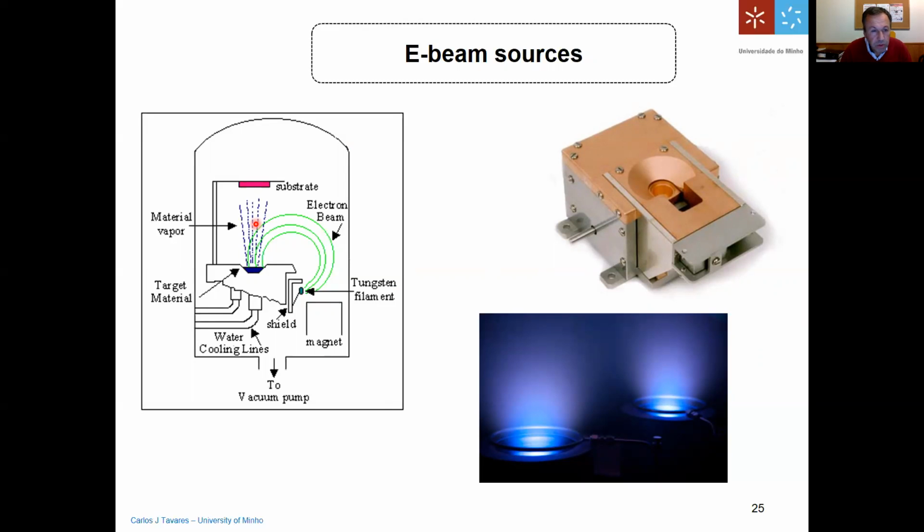For example, if you want to make titanium dioxide, you can do this both ways. You can have just titanium small particles, like titanium pellets, and then you need to feed some oxygen. So that when titanium melts and evaporates, it will chemically bind with oxygen and react and form this titanium dioxide molecule, which will be depositing on the substrate.